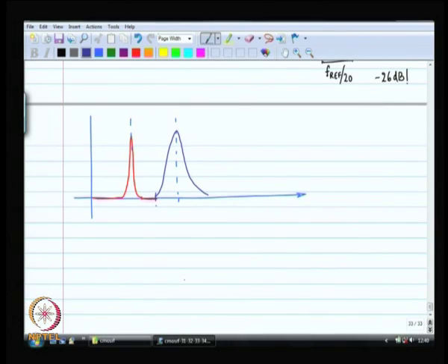How is the spectrum going to look like? Any guesses? The spectrum is going to scale in the x axis by a factor of 2. So, this point will translate to this point by 2, this point will translate to this point by 2. Every point is going to translate to that point divided by a factor of 2. Okay? So, you are compressing the x axis by a factor of 2.